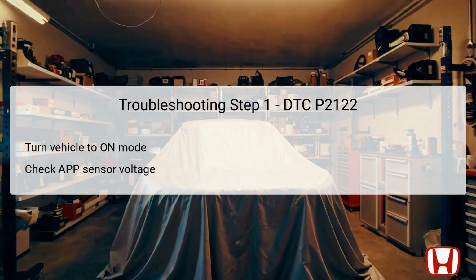By verifying the voltage at this stage, technicians can effectively determine whether an issue exists with the APP sensor itself or its related circuitry. Interpret the data displayed accurately to decide on the next course of action. Should a low voltage be confirmed, it will reaffirm the presence of a fault that warrants additional investigation.